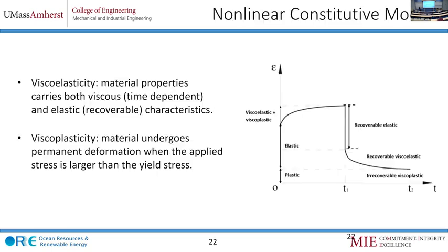So, viscoelastic model. As we saw in the previous graphs, the system is not purely elastic, and doesn't come back as quickly as it goes, but actually relaxes. If you hold the tension for a while, the system relaxes, and then the tension kind of flattens out.